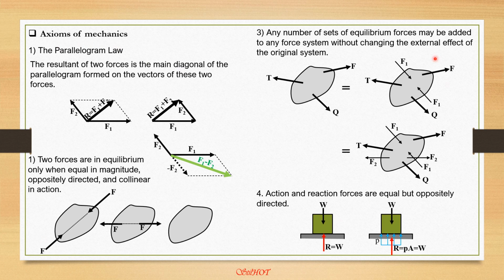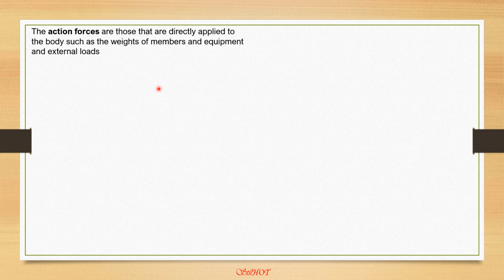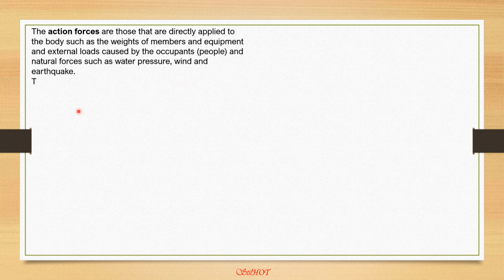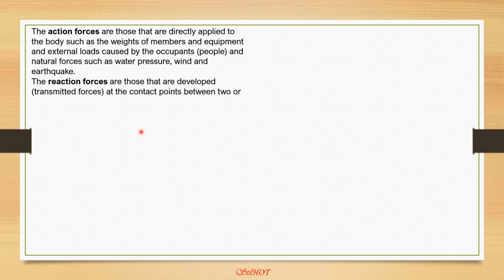And I hope that you recall all these axioms of mechanics because these are very important in the analysis of force systems. So again, the action forces are those that are directly applied to the body, such as the weights of the members and equipment, and external loads caused by the occupants, people, and natural forces such as water pressure, wind, and earthquake. The reaction forces are those that are developed or transmitted forces at the contact points between two or more contacting bodies.